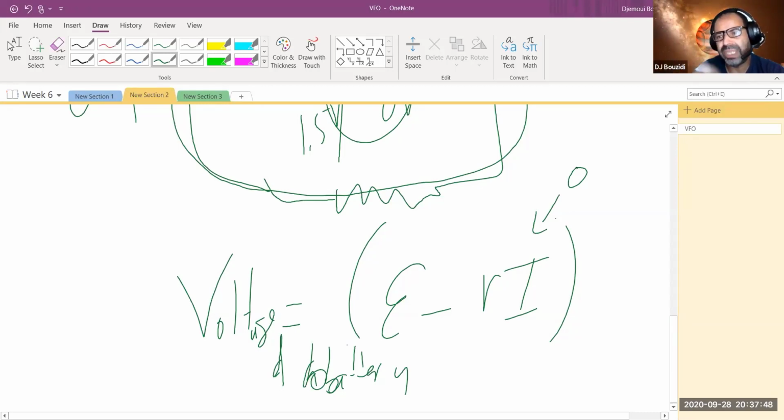You will see that in an actual lab. You have a power source battery, for example two 1.5 volt cells, meaning 3 volts. You measure its voltage and it reads 3 volts, or very close to it. You connect the resistors and everything else, and the same voltmeter that was reading 3 volts will read less, because of the internal resistance. Internal resistance could be due to the connections or internal processes, because all of this has all kinds of connections in here and there. So that's nature.